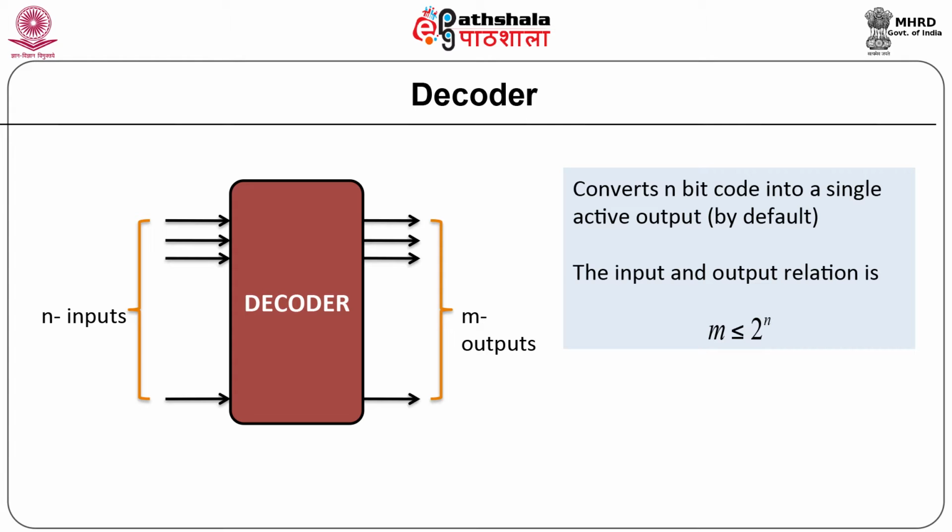A decoder is a logic circuit which accepts a set of inputs that represent a binary number and activates only the output that corresponds to the input binary number. In other words, a decoder looks at the inputs, determines which binary number is present and activates the one output that corresponds to the given number. All other outputs will remain inactive.